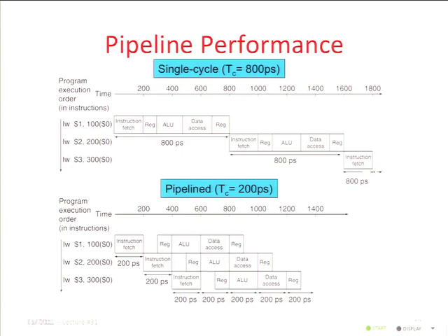When we say we're going to memory, we don't really mean that. We mean we're looking in the cache, and only if there's a cache miss do we look in the next level, and only if it's not there do we go to level 3, and then finally to memory. So we try everything we can to avoid going to memory. But level 1 should return within that 200 picosecond budget.